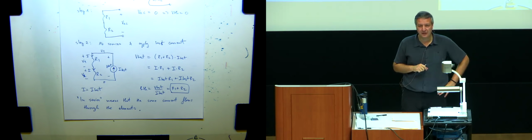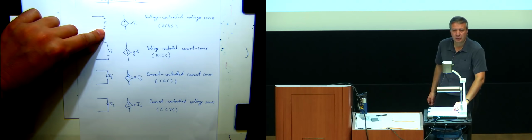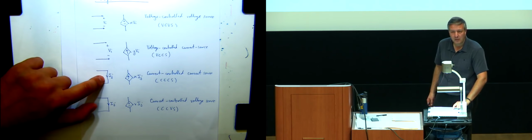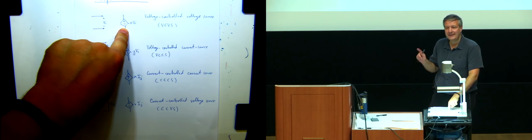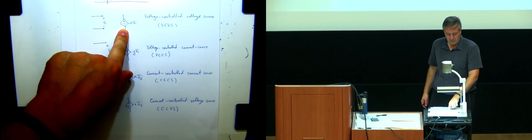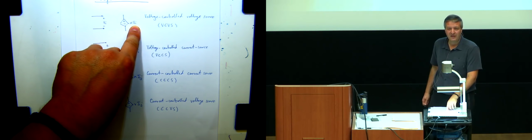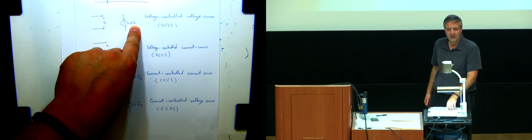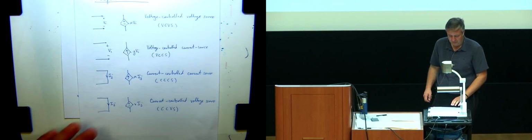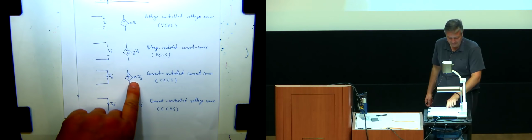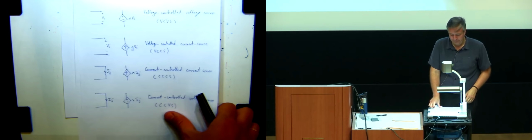So what was our definition for a dependent source? Yeah, it was what I drew here, right? There is some control voltage or current in the circuit, in one of the elements or between two nodes, that defines the value of the source in that same circuit. Just defines the value. Now, this is a battery whose value is alpha V1, Vi. So the voltage produced at the output of this is alpha times Vi. Or the current produced by this source is alpha times Ij, where Ij is some current somewhere in the circuit.